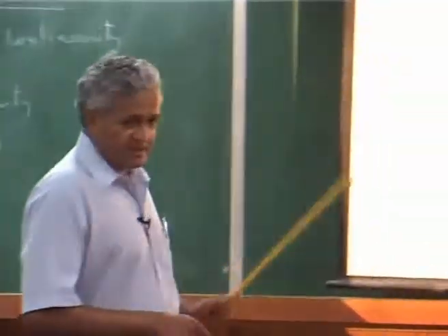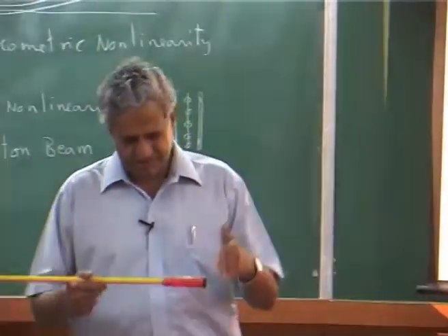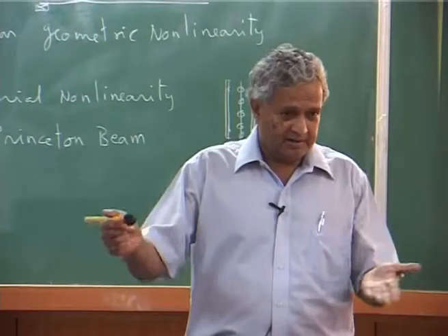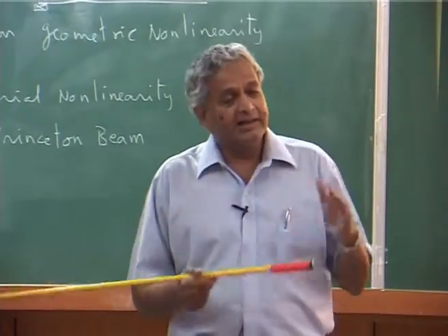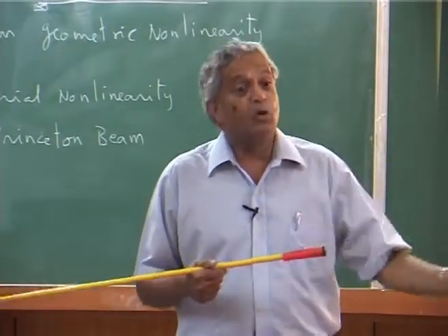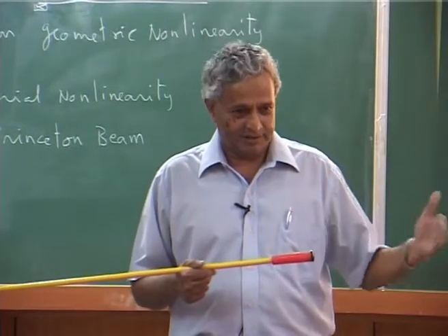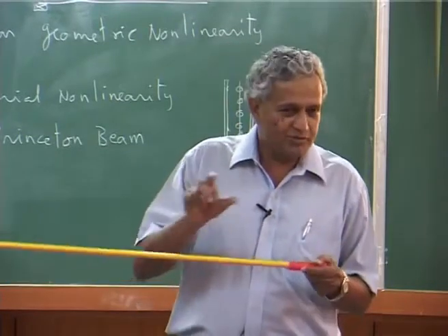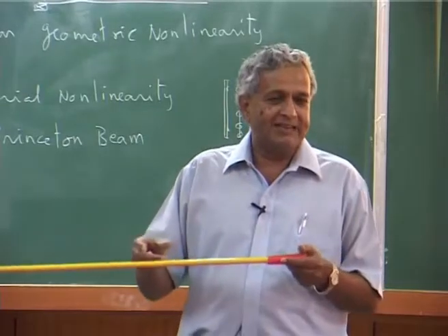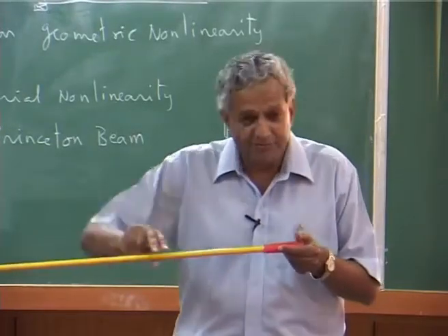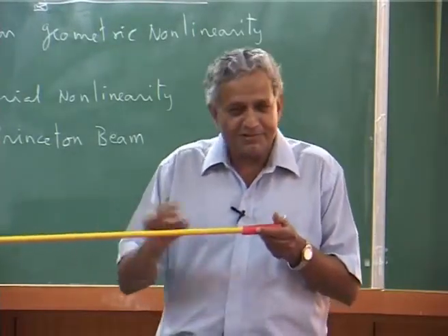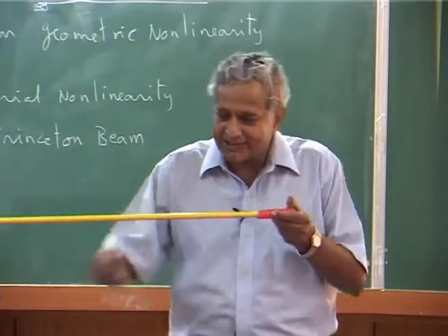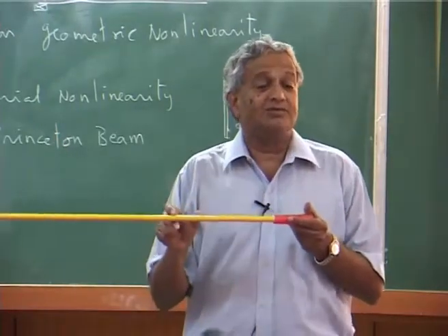But most of the hingeless blades, actually pretty much, because I know the ALH blade, the pitch bearing is inboard, okay, and there is no flap hinge per se, but there is an equivalent flap hinge, where some stiffness drops at some section and that becomes kind of a hinge.